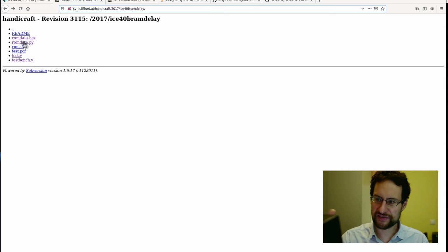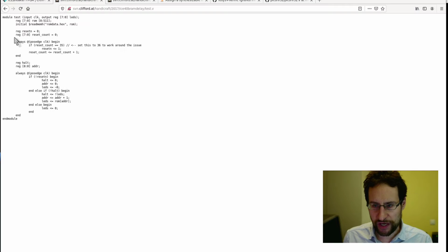Also, there is apparently some block RAM initialization delay. You can initialize the memory on the FPGA to something, and apparently there's some initialization delay of some clock cycles, also fun stuff that you find. I was only inspired here on how to define larger resources. It took me a little bit of Googling and trial and error.